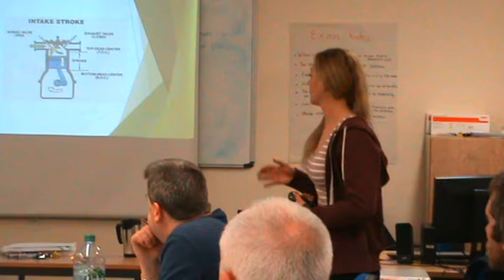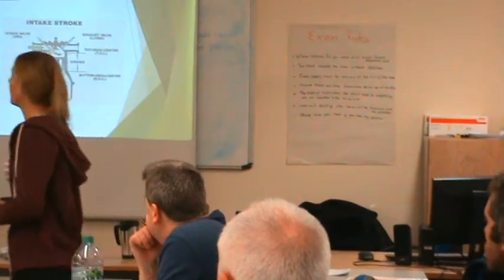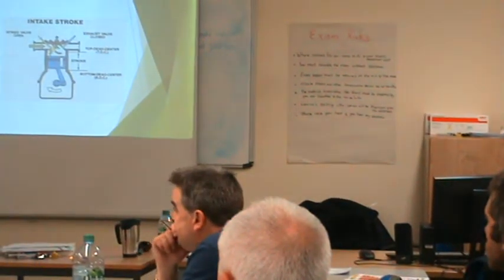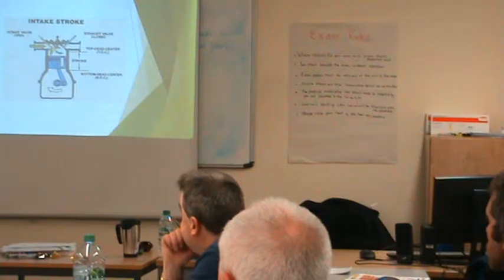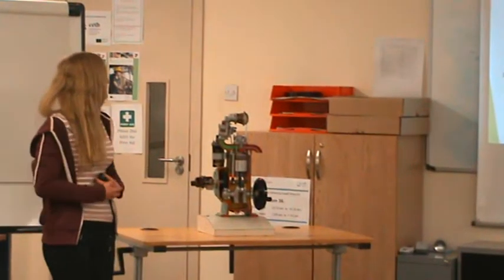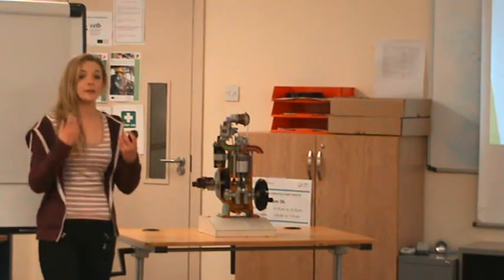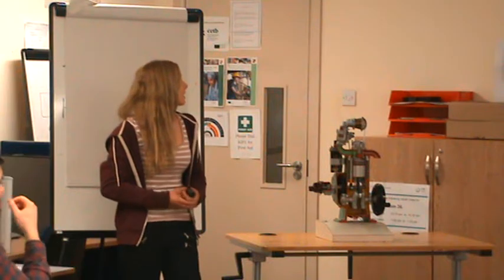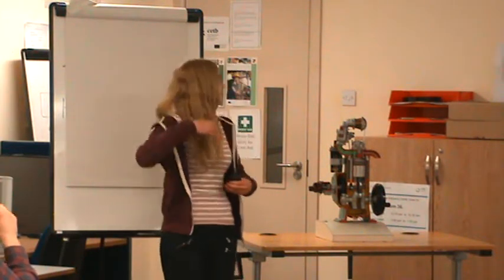So next I'm going to talk to you about the 4 strokes. The 4 strokes are induction, compression, power and exhaust. So the first stroke here, the induction stroke. The intake event is when the piston draws in the air-fuel mixture and fills the combustion chamber. The intake event occurs when the piston moves from top dead center to bottom dead center and the inlet valve is open.